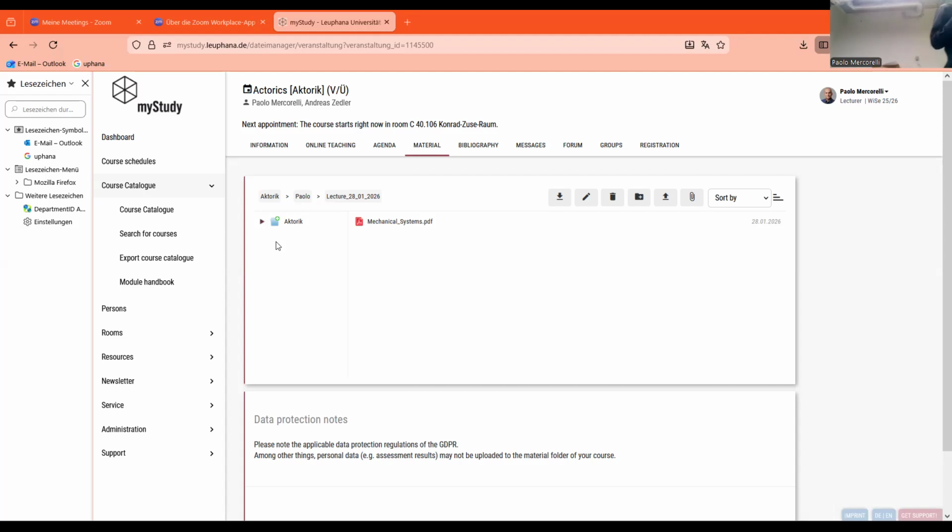You have two masses moving in a horizontal way, and we can see that the two masses are connected together with a damping factor, and they are connected to the external walls using springs, characterized by K1 and K2 spring parameters. D1 and D2 are the damping between the mass, once with respect to the left wall and once with respect to the right wall.